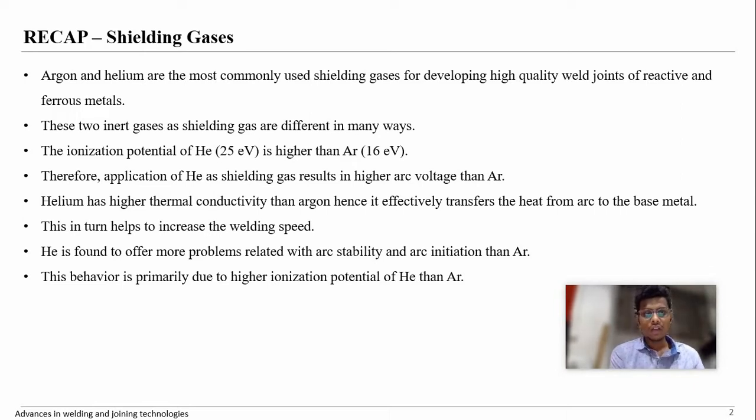So first of all, shielding gases: for any arc welding process, like autogenous welding, tungsten inert gas welding needs shielding gas, especially the inert gas. And also, if you go for deposition welding, whether it is metal inert gas welding, or even laser welding, or plasma arc welding, there will be a shielding gas. Sometimes even in laser welding, shielding gases are used.